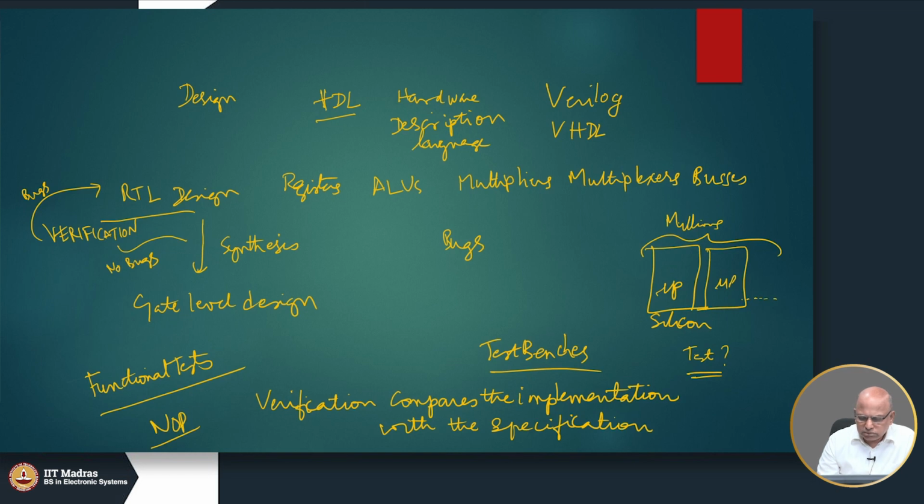And the microprocessor's functionality is fairly complex. It usually has a number of different instructions: move, add, subtract, multiply. If you look at the ARM microprocessor for example, there are many instructions: logical instructions, arithmetic instructions, branch instructions, data movement instructions. Now, can we really go and write small functional tests to test each one of these functionalities?